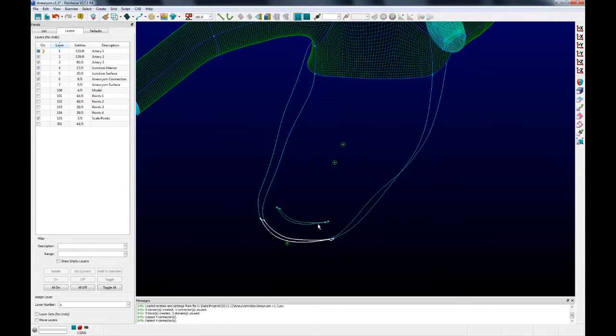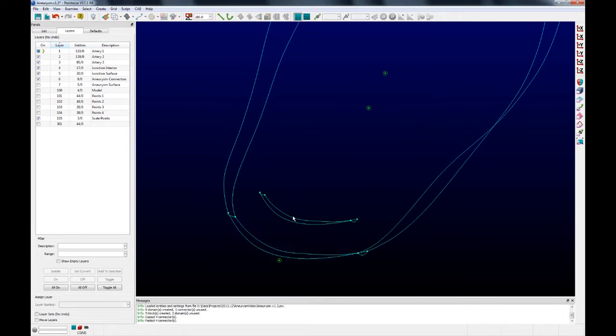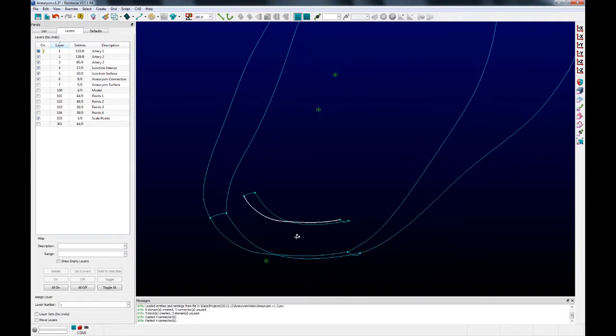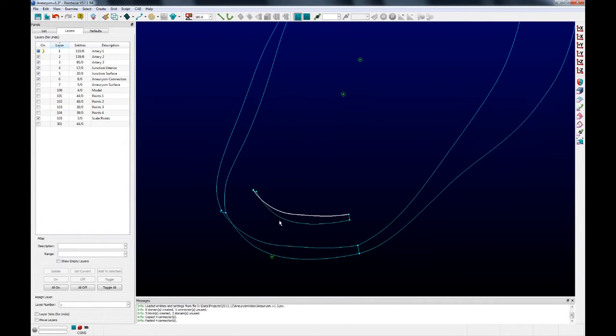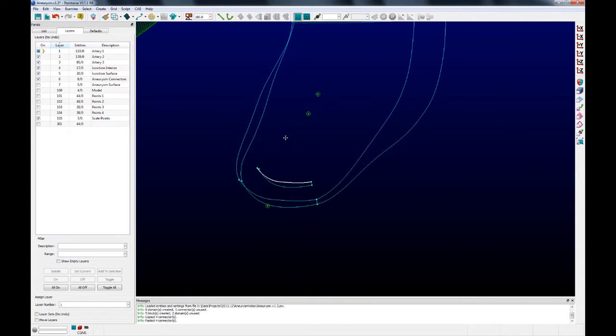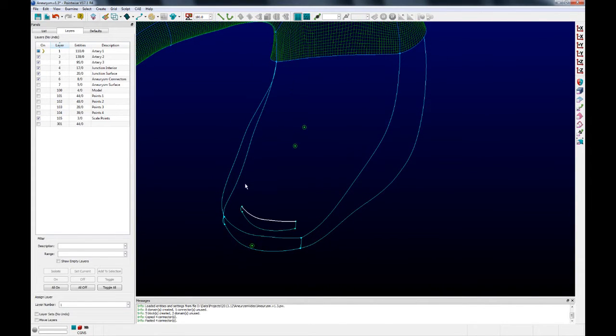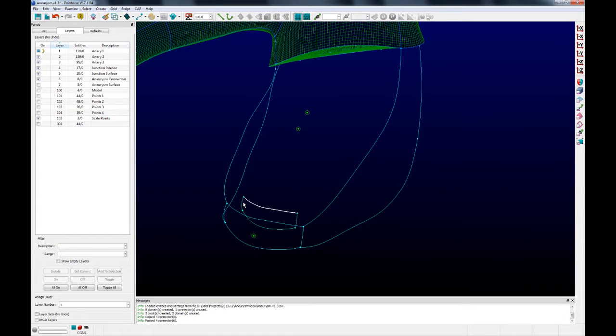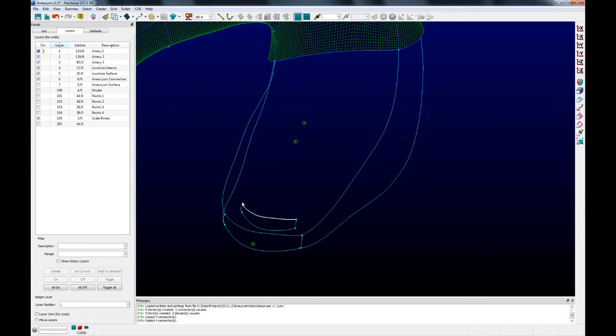But for reasons that'll become clear a little bit later, we're going to go ahead and actually remove the control points for these curves. The reason being, whenever we go in and create the topology to connect this inner H block, we don't want to have a very smooth corner here because that is going to be the corner of a cell, and you want that to be a nice right angle ideally.